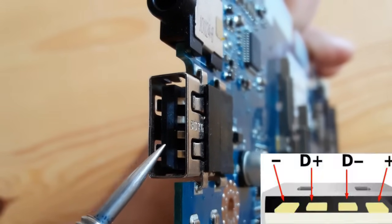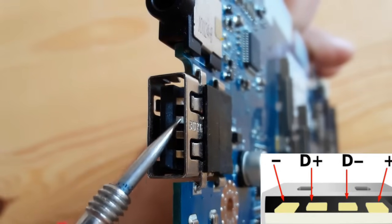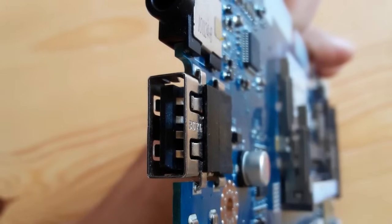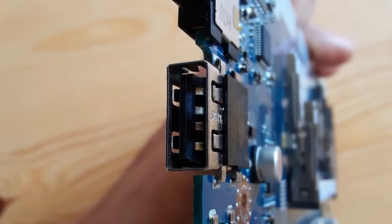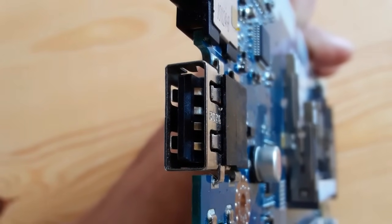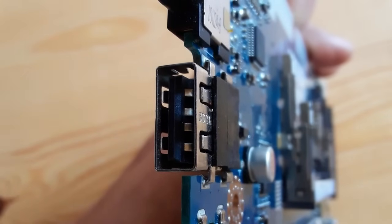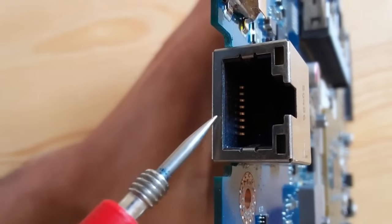This connector contains the ground, the plus 5 volt, the D minus and D plus, I mean data plus and data minus. When these pins inside this USB connector are broken or bent or damaged, you can get a failed motherboard, especially when two pins touch each other.